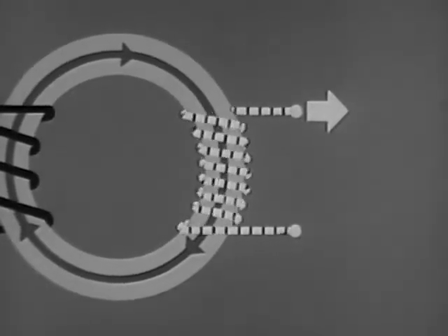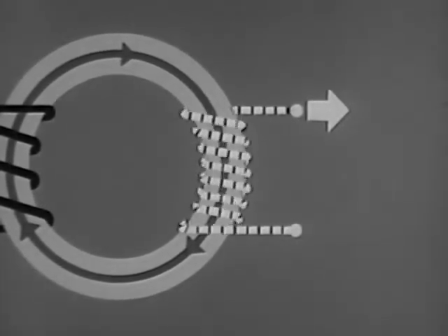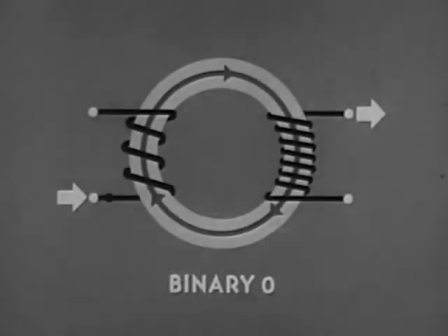Observe the direction of current flow, out the top of the winding. The way these two conductors are wound, a pulse of current sent into the bottom of the input winding results in a pulse of current going out of the top of the output winding. We used a dot to keep track of the polarity of the input winding, and a similar dot will establish the polarity of the output winding. This gives us another rule about the dots in a magnetic core diagram.